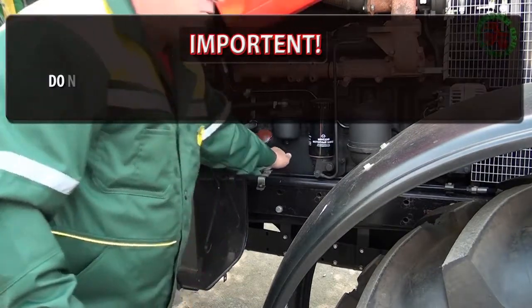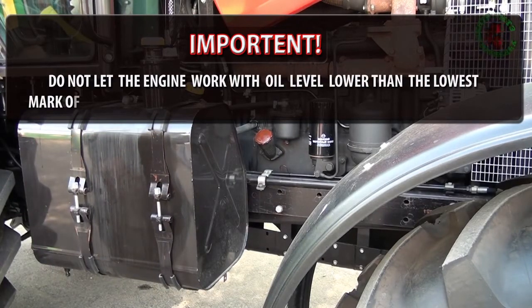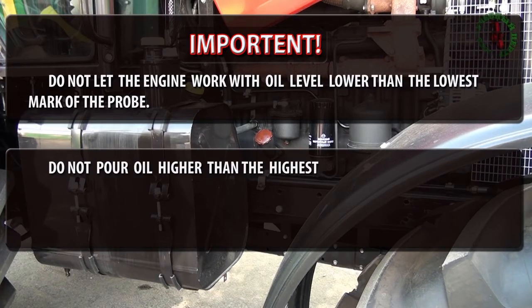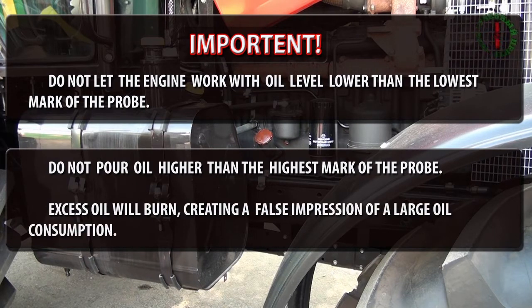Important! Don't let the engine work with the oil level lower than the lowest mark of the probe. Don't pour oil higher than the highest mark of the probe. Excess oil will burn, creating a false impression of large oil consumption.